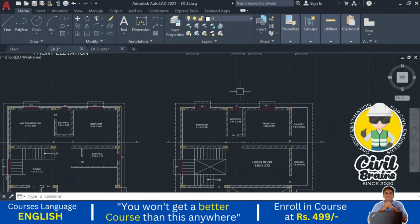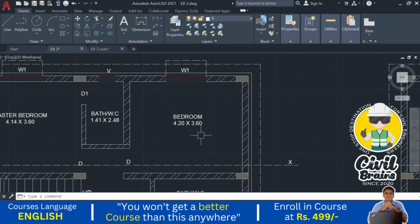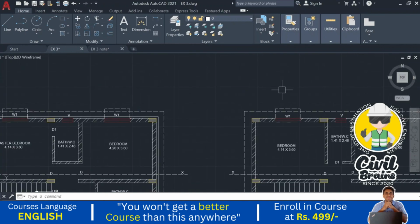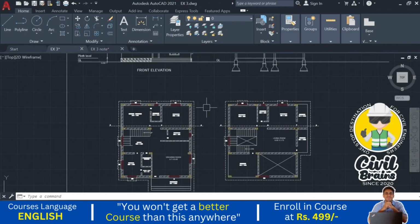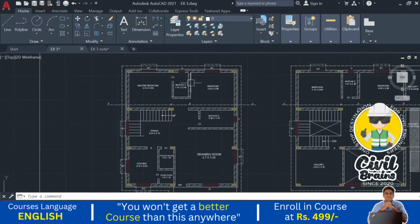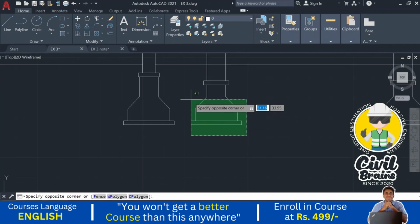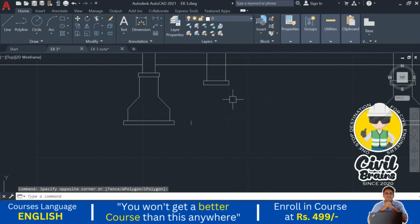And next if you come to the third wall here, that is also the same main wall, we are considering it a main wall. So now here we just see this one. We come to the section here. Now you just see this wall is cutting, but here there is no column, correct? So there is no column, which means we need not show the column over here. Clear or not? So we need not show the footing over here. Just delete it.